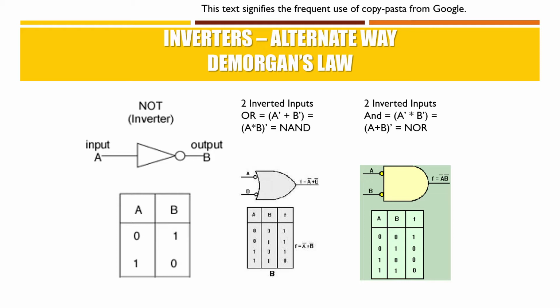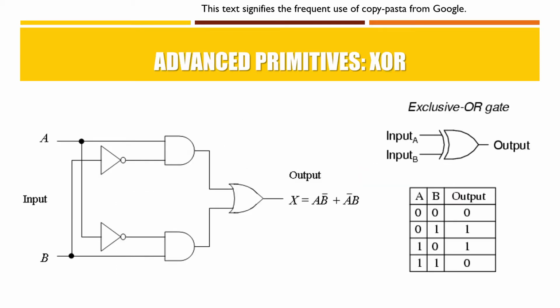All the primitives before this have used one logic gate or logic gate connected to a NOT gate. Now we're going to use a combination of these gates to create one primitive. And this is why this is referred to as combinational logic, because I'm attaching a combination of logic to create more logic. This primitive is known as the XOR, and knowing the insides of it is a lot more complicated than knowing what it actually does.